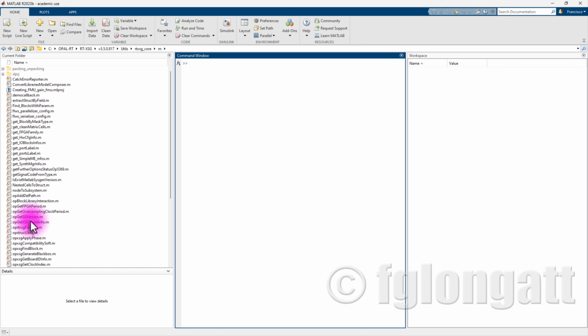So here we are inside MATLAB. This is the classical environment for MATLAB. You must identify that here at the top we have the toolbar, and there is an icon over there to start Simulink. So what I suggest is that you start Simulink and create an empty model.